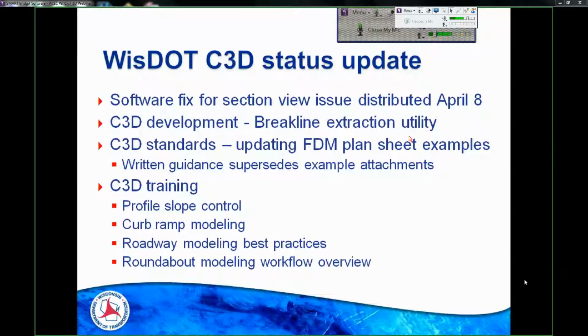Very, very neat idea because a big part of refinement surface processing was to go back through and readdress all of the daylight slopes. You might have slope transitions going from a 2.5 to 1 to a 4 to 1 in one corridor frequency, right? And that's 10 feet or 25 feet or whatever that frequency distance is, much too fast for that transition. This workflow helps you build those slope transitions into your base design. So that's a very interesting, very creative way of using what we have in Civil 3D to make roadway design life easier.